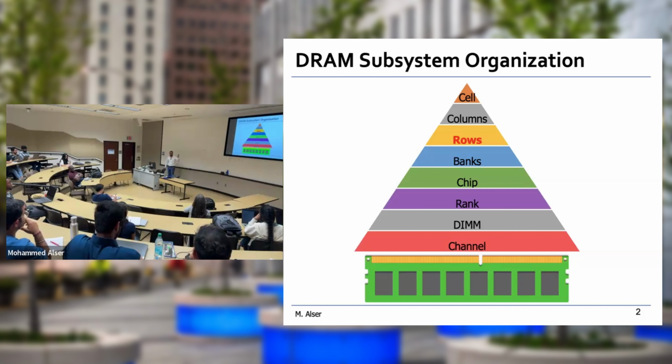All DRAM chips in a rank have something special. That's why we have a category called rank. What is that special thing? We discussed it last time toward the end of the lecture. There was a very nice example of how we can fetch the data from a rank. We said that at a single clock cycle, we can get one piece of information from a single chip.